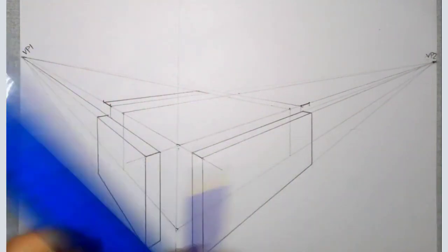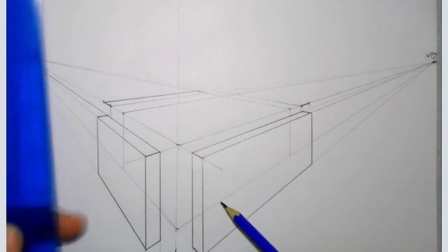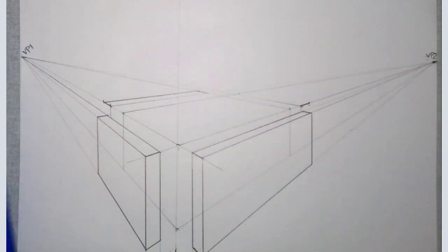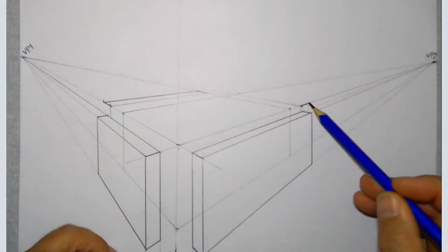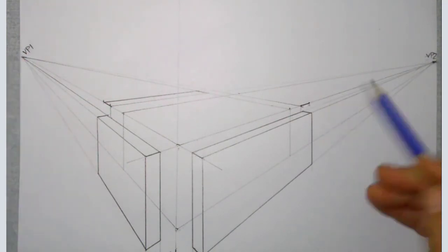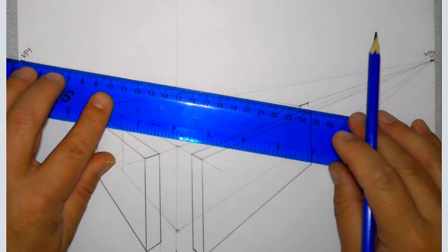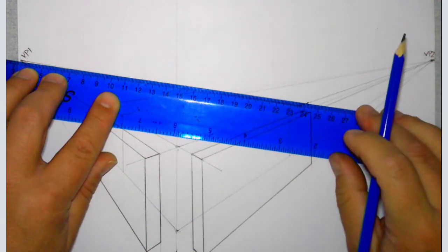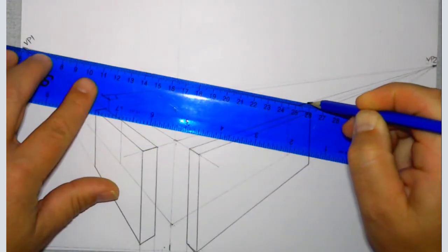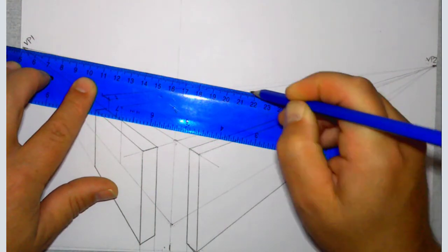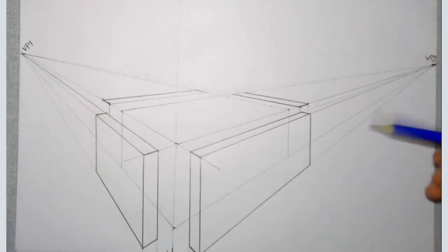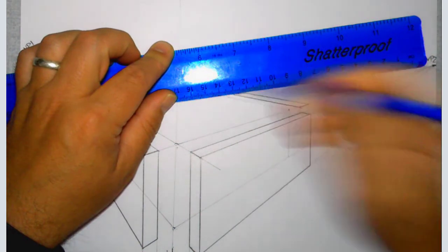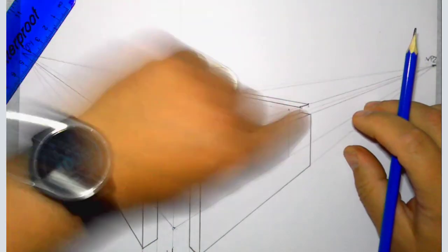And at no point am I deviating from my perspective lines on this. Sometimes you might plot between. If you're not going to a vanishing point or you're not going vertically, then you're probably going wrong. Right. So let's take this one here off to VP1, and that one there off to VP1 as well. Okay. And again, I'm just going to darken that in. So that's dark, that's dark, that's dark, and that's dark. That gives us our definition.